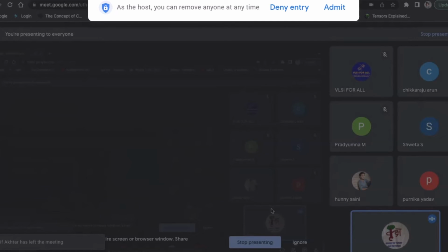Okay, so in verification, we do full exhaustive checking. In verification, there are two or three topics, like verification through simulation. We can do simulation only. In simulation, we have two different types. In one, we can apply a test bench using Verilog, and the other is we can apply SystemVerilog to test it, or UVM, universal verification methodology. Then we can also use other languages like E, Vera, and we can use the C language to do the functional verification.